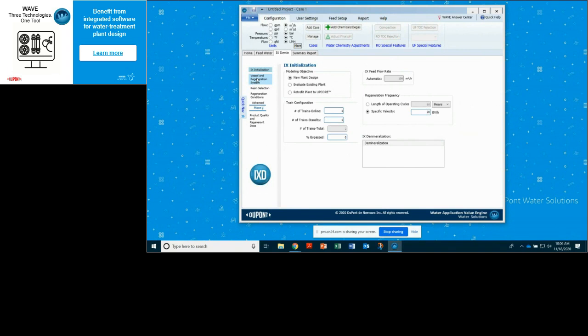Yeah, so in most power applications, Donna, thanks for the question. For condensate polishers, we would look at linear velocity as the guiding max flow range, usually around 50 GPM per square foot. And maybe Garth, you know that offhand in metric. But for UPW, you'd be looking at a lower range, more like 25 GPM per square foot as a max. So in designing things with much lower TDS, your BVs per hour would be much higher. Yep. So keep that in mind.